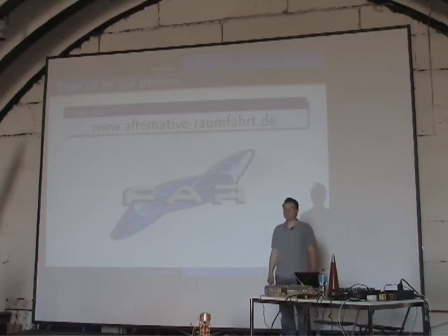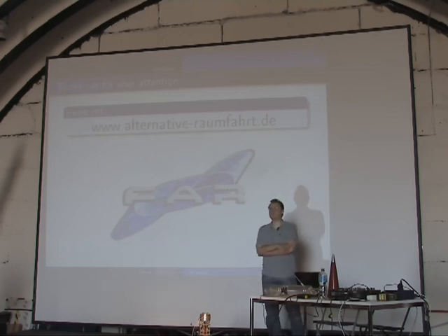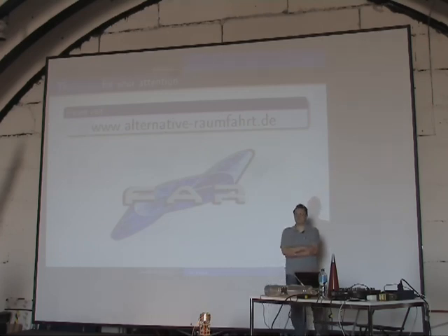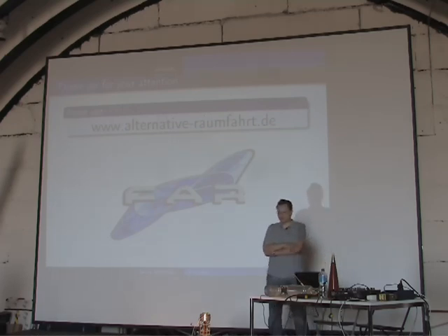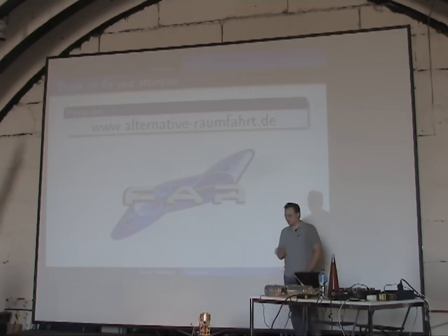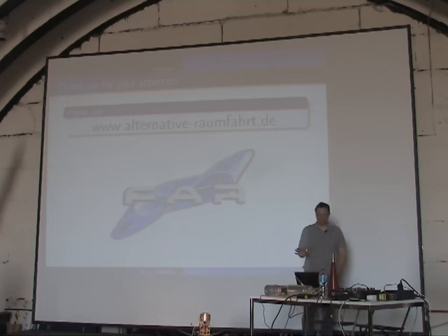How tight is your energy budget? I saw on the schematics linear voltage regulators, and they are known not to be very efficient. Yeah, but they're not very efficient, but they don't produce noise. Noise is the most important thing. Of course, we could use other regulators, but if you use buck boost or something like that, you would introduce a plethora of noise at 100 kilohertz and more. It depends on the switching frequency. So these kinds of regulators, you cannot use them in avionics. It would just flood the whole system with dirt, with noise.